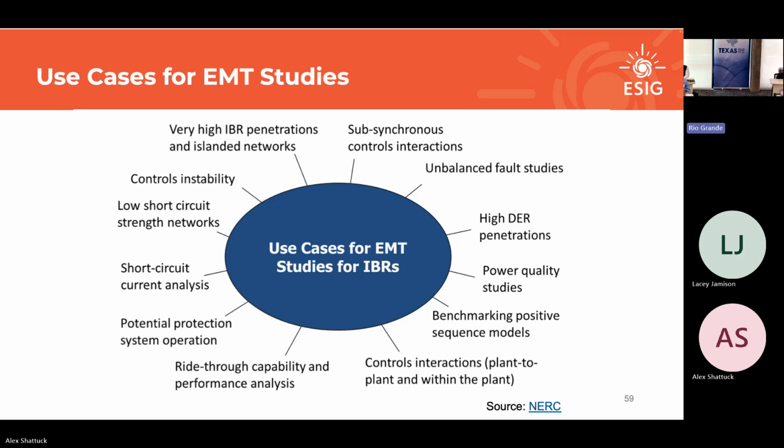Texas is an island network, Hawaii is an island network. That just kind of makes everything worse, for lack of a better term. So those needs for the EMT domain are very important there. SSCI, subsynchronous control interactions, unbalanced faults, power quality, controller interactions, all things we talked about. The detailed behavior and ride-through, very important. A good use case for EMT.